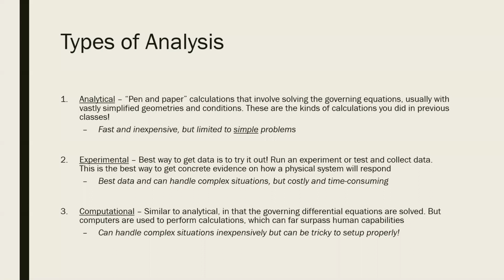But the downside to computational is that it can be really tricky to set up properly, and it can actually lead to a lot of misleading results. What can happen a lot of times is, for people who aren't really trained in finite elements or trained in the software, they can run a simulation on ANSYS, but they might get a result that they think is true, but they set it up all wrong, and it's actually more dangerous. So the downside to computational is that it can trick you into thinking that the results are good when it's not really. So in order to use computational, you really have to know what you're doing in order to set up the problem properly. And that's what this class is going to be all about.